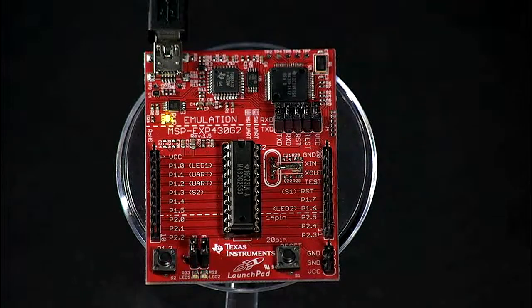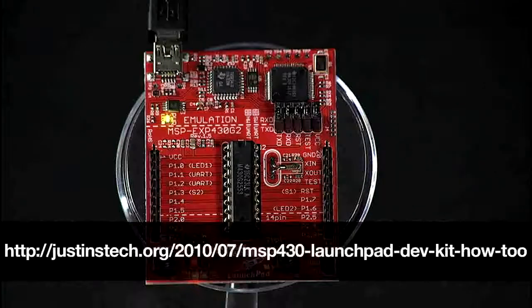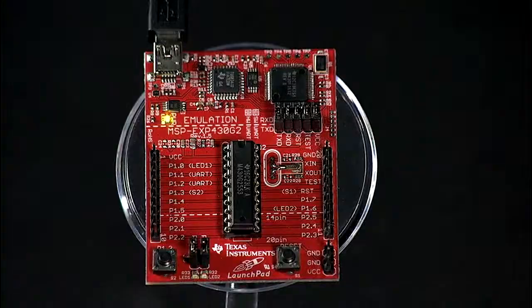The small size makes it extremely difficult to manage and move the crystal around efficiently, so you may want to use some tweezers and some tape to arrange it on the board. Be sure the leads make contact with the pads. I used a magnifying device to ensure it was lined up correctly. Solder the leads to the two small pads and the opposite end of the leads to the larger pad. There is a link shown below of how one of our folks that was using the board went ahead and soldered the crystal to their board. You can go ahead and look at that.